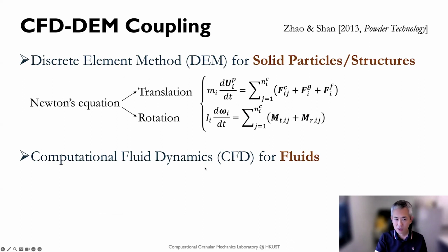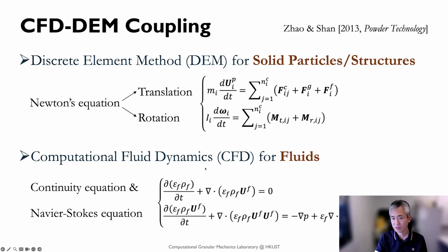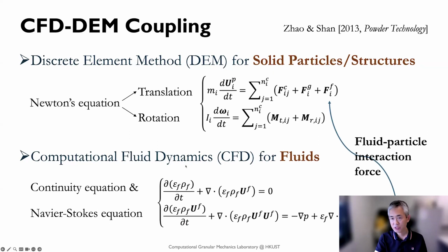Okay, and also we use computational fluid dynamics to model the fluid involved in debris flow here, and essentially CFD will be used to solve the continuity equation and a locally averaged Navier-Stokes equation here. And then we consider the interaction between DEM and CFD and exchange the fluid-particle interaction forces here, right?